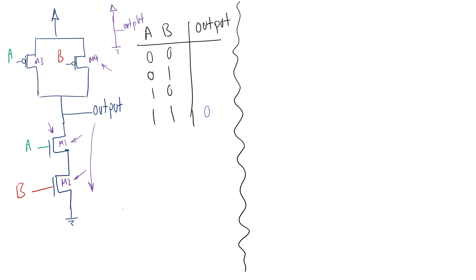Well, this is a situation that we never want to happen. And in the circuits that I'm going to provide to you, this will never happen. We're not going to have any situation where VDD and ground are racing to set the output or to force themselves onto the output. There's always either VDD or ground connected to the output, and never both of them.